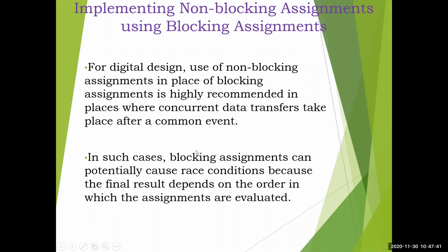Just to summarize, for digital design, use of non-blocking assignments in place of blocking assignments is highly recommended in places where concurrent data transfers take place after a common event. Whenever you have a concurrent data transfer, it is better to go for non-blocking assignments. In such cases, blocking assignments can potentially cause race conditions because the final result depends on the order in which the assignments are evaluated. So we could not use blocking, because it will bring a race condition there.